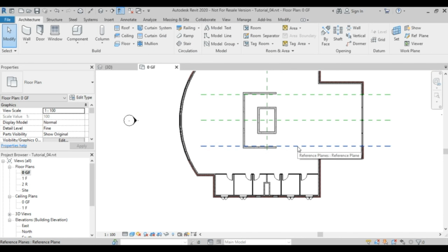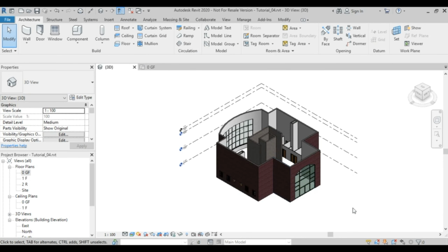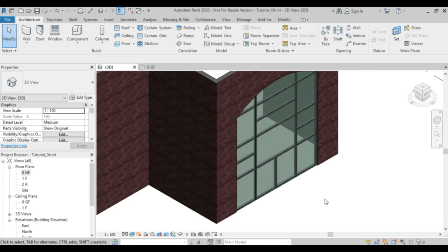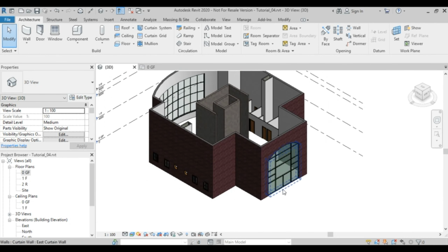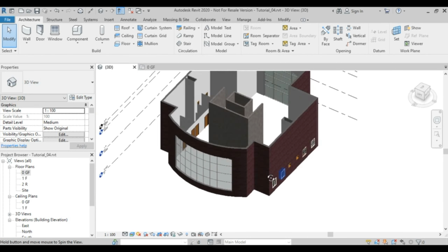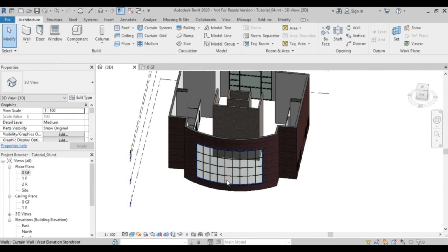We will do the next thing using the 3D view. It's easier for everybody. What we want to do is insert a door here and a door here, as if it's the main entrance door for the building, and we want to insert windows over here, which will be as an awning window.